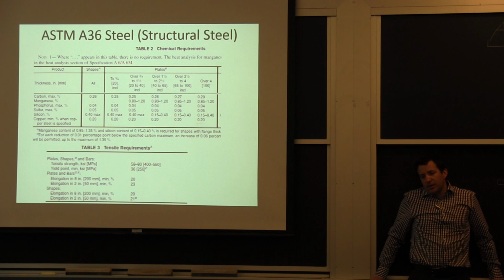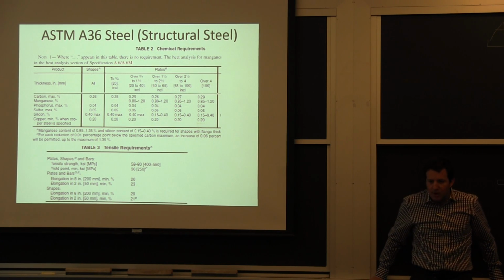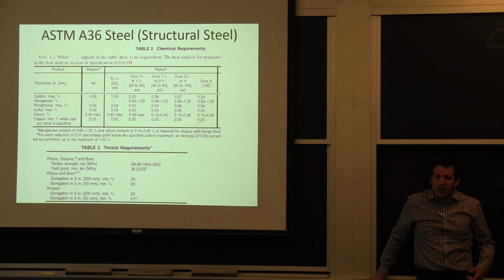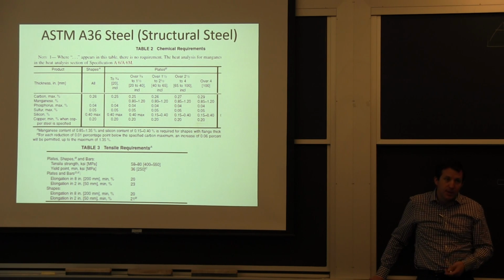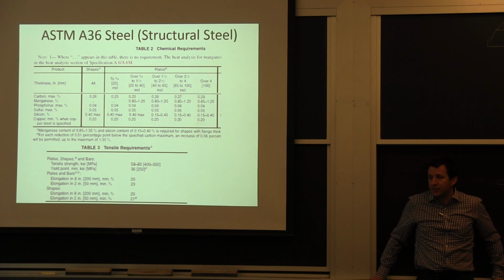And as a safety precaution, we always had more non-destructive testing after the fact. So if there was any problem of picking up of hydrogen or anything during the welding process, getting some little cold crack under the surface, by ultrasonic testing, we were able to point that out after the fact.